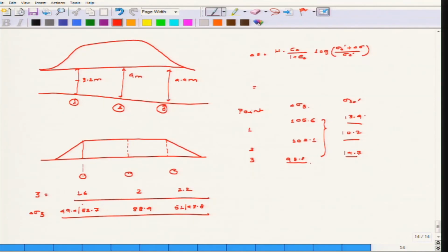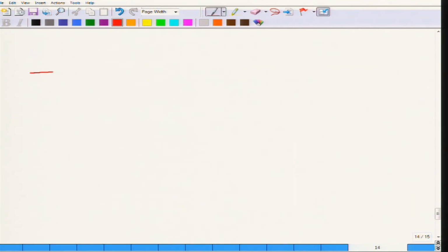So, at mid height of the clay layer, that means 6.7 with 1.6, and you will get 13.4, similarly with 2 and similarly with 2.2. Once you multiply all these, sigma final, or sigma naught plus delta sigma, will be equal to 119, 112.8 and 113.5. Now, just plug these values and you will see that a settlement profile like this is obtained.